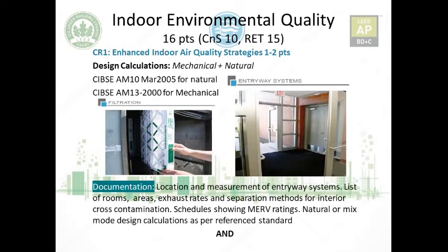Another strategy is to have design calculations for both mechanical and natural ventilation systems, and the standard is by the Chartered Institute of Building Service Engineers, with these standard clauses or addenda. If you search for CIBSE before, maybe it will elaborate further here. You can see the filtration, the MERV filter we were talking about before. This is the figure, and the entryway systems. It might give you a better idea after watching this figure.